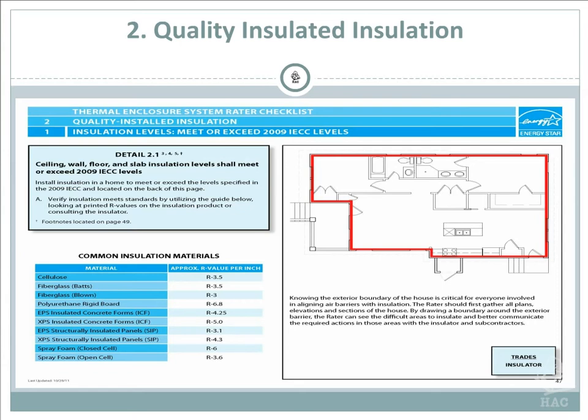The SIP panels, depending on what the thickness of the SIP panel is, if you've got a 4-inch or a 6-inch SIP panel, you're coming up to about an R24 in the walls, and that's just with the SIP panel. So depending on what material you're using, what R values you're trying to reach on your installation, these are the things.